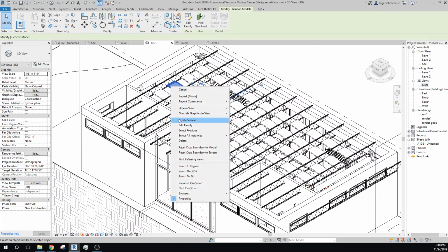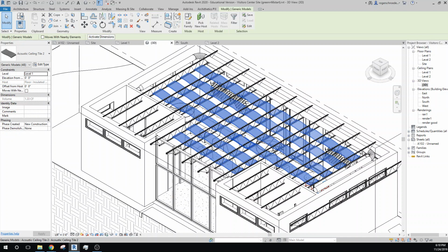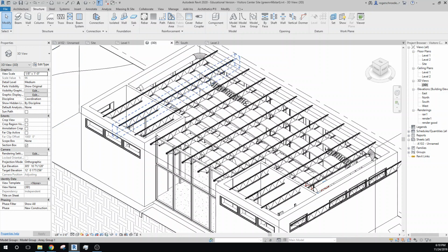Let's move our ceiling down so it gets out of the girder area. So I'm going to select all instances visible in the view and set their elevation. Let's just try -1. Oh, actually, it occurred to me, we have to correct the overall elevation of these because these are objects that are based on the floor level.